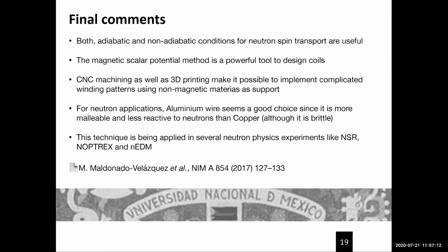That part is actually the most complicated in Comsol because we have to export the solutions, these contours, and then somehow in a new model make them current paths, and then we use the AC/DC module.